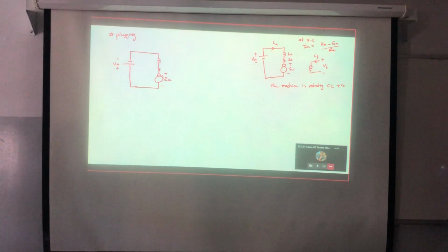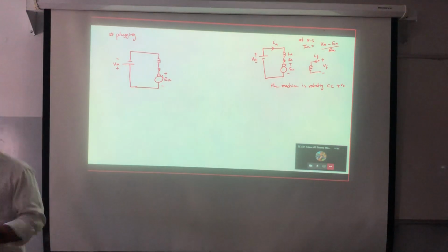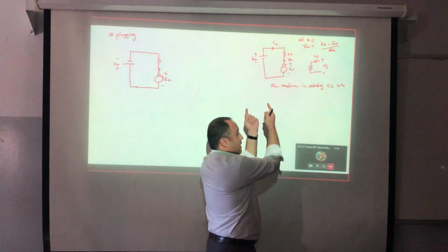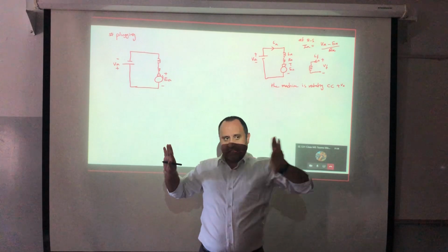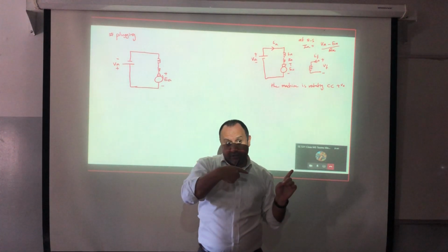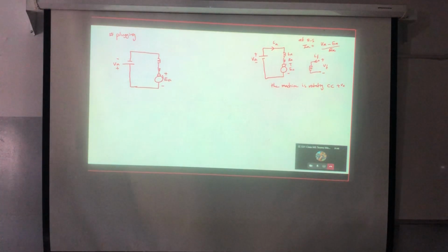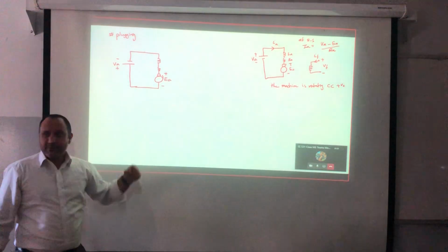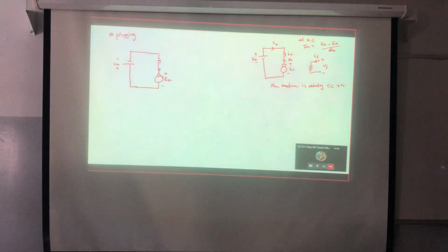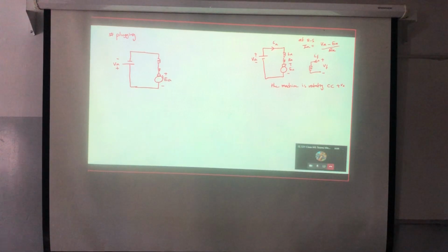Now here, those two supplies resisted each other in the first scenario. Let's assume that VA and EA are two supplies. Are they resisting each other or supporting each other? In the first case, resisting. Here, they are supporting each other. So similarly, the current will flow in the opposite direction, correct? Very, very high current.